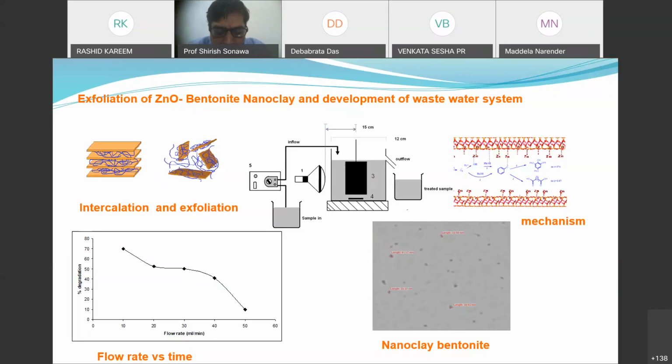Actually, clay, if you look, the smectite-based is the major origin, and all the clays have the common chemical name aluminosilicate, in which alumina and silica are there. If you look at normal clay in India, most of the clay available is a bentonite kind of clay. The sources of clay are mostly in Kutch and Rajasthan. These are the two major sources.